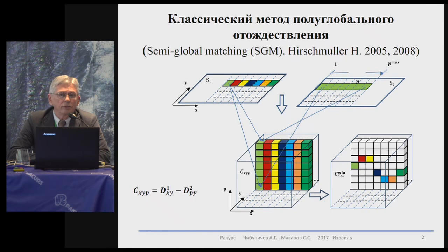So, based on the elements of external orientation, this stereo pair is transformed, and as a result we get the following situation. Each pixel on the left image is placed on the relevant line, on the basic line of the right image, which helps us in better matching the points. And our main task is to find the matching of each pixel on the left image and find its matching pixel on the right image.